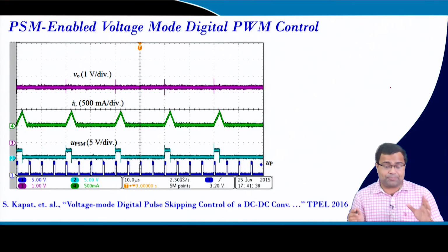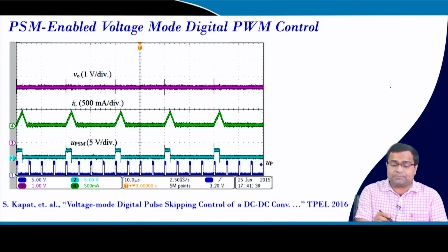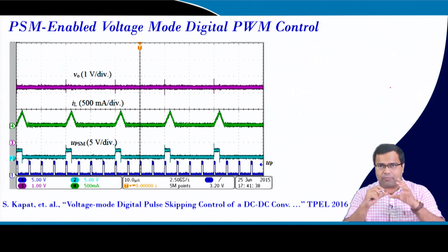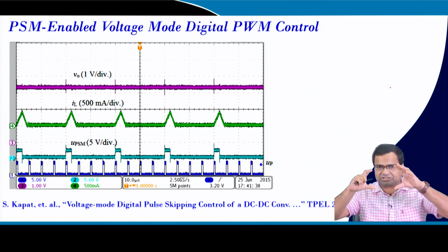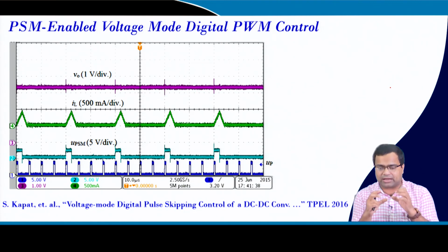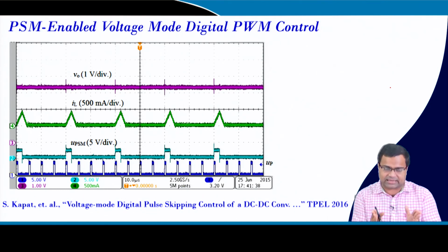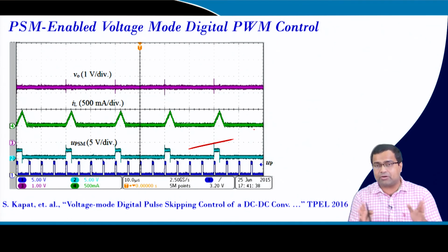The other technique we have also proposed is one in which you can reconfigure the voltage control pulse skipping mode, where the number of charge and skip pulses is set. We saw in pulse skipping there is a non-monotonic spectral composition, that means the waveform was not repeating in every cycle, there are slight changes and it creates some kind of high periodic behavior. But if we can configure the number of skip cycles and charge cycles, in this technique you can set it a priori, by which you can optimize the energy, efficiency, and you can achieve perfectly periodic behavior.